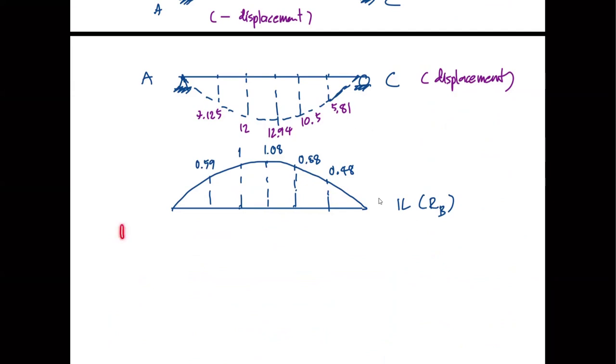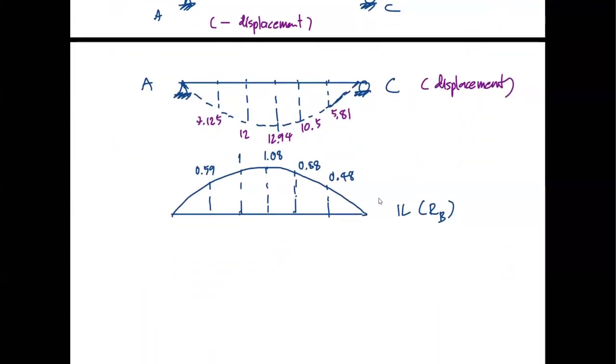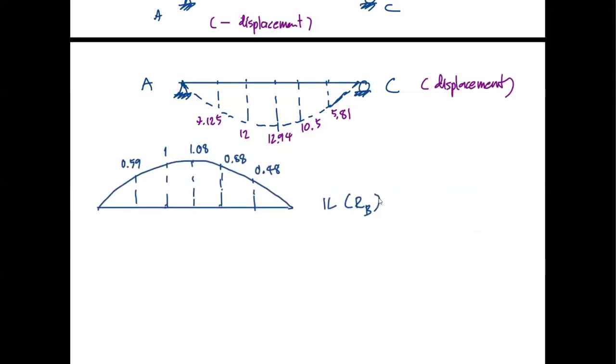RA. I'll try to use the left side, maybe because we are on a different page now. I don't have to draw directly underneath those. So let me try to move this to the left a bit to create space on the right. So now RA. Remember that now you know RB. So how do you obtain RA? You take sigma Mz equal to 0, right? Isn't that the most sensible thing?